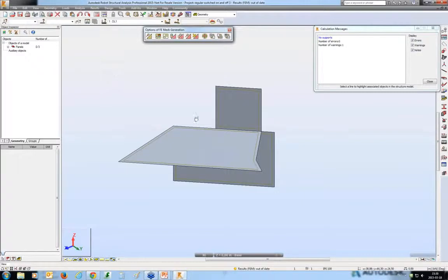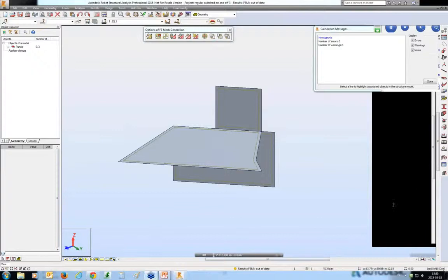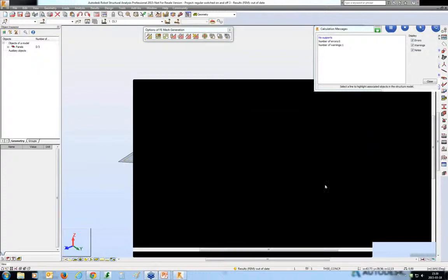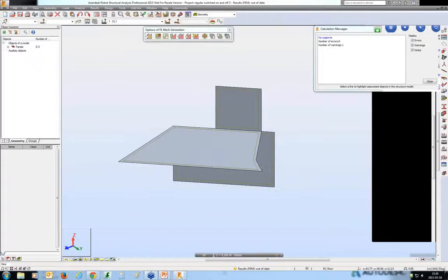Okay, all right, let's see if that answers that. The next one: do you have some recommendations for analytical models in Revit? A lot of problems you showed are caused by analytical model issues. Yeah, I think the first option that I covered, the adjustment to structural axis, is the one to start with.